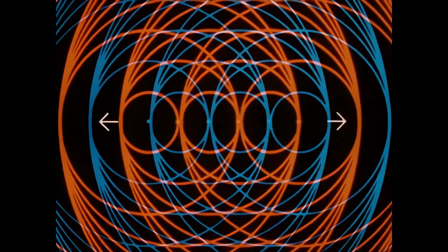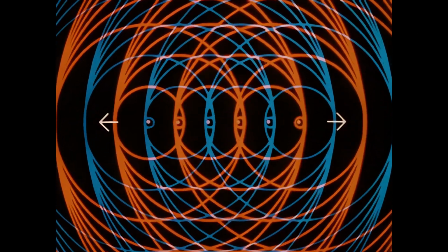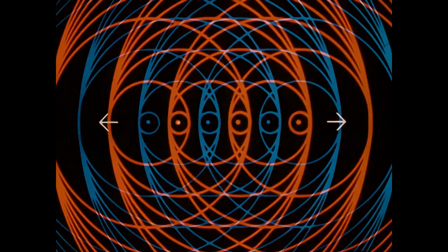In some cases, however, it is desirable to concentrate the radiated energy in one direction. To see how unidirectivity can be achieved, let us return to the simple dipole. A quarter of a wavelength from it, we add an undriven element which acts as a reflector. Again, we can view the elements from above.